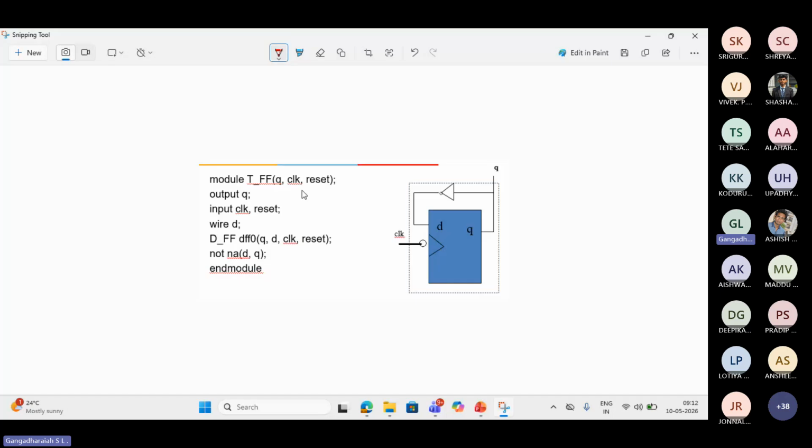Generally, what designers were doing before, there was a lot of confusion between wire and register. Sometimes in place of wire, if you declare reg, it used to throw a lot of errors, and the functionality also could differ in some cases. This was the problem designers were facing, because you have millions of lines of code. In place of reg, if you declare it as a wire, you will have to rework, and spend too much bandwidth on it.